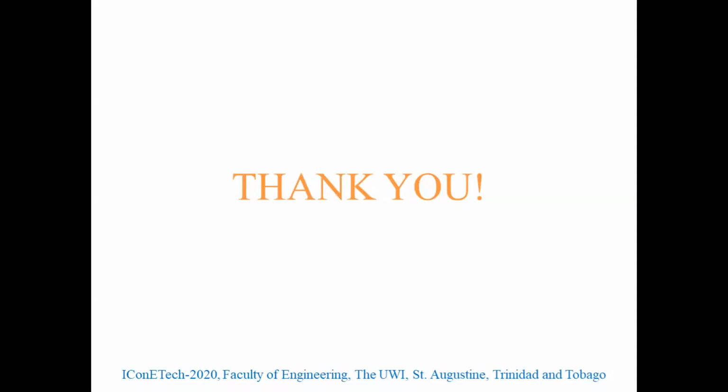Thank you. And then you looked at cross flow and perpendicular flow. Yes. What would you be more likely to use in a filtration plant, and why? How would it affect the design? Okay, in the surface water treatment plants in Trinidad, we have rapid gravity filters, which use sand and gravel filter medium, right? So that flow is perpendicular. And the problem they are experiencing at present is that the filter medium becomes easily clogged.